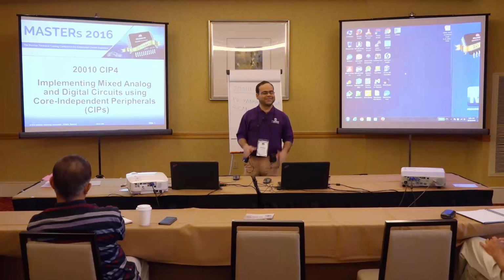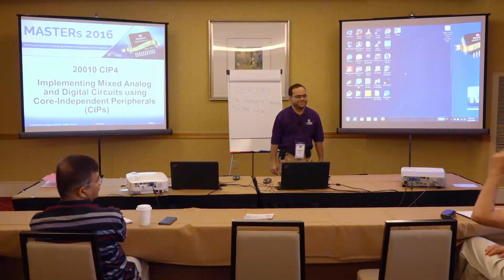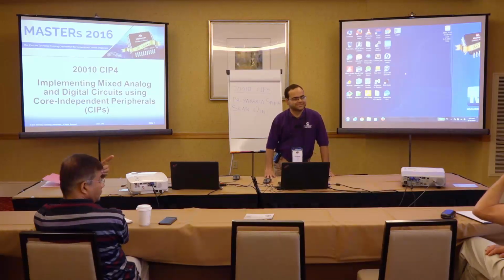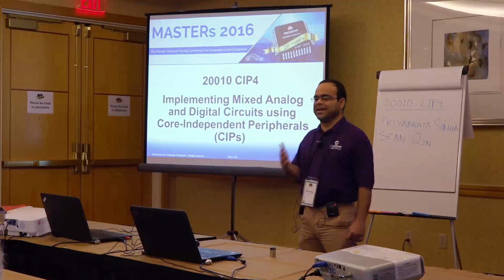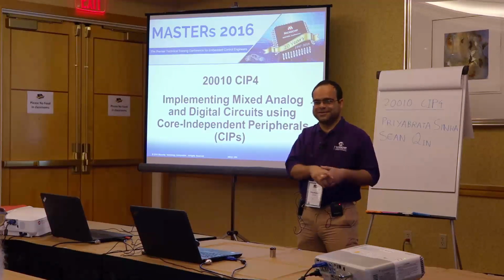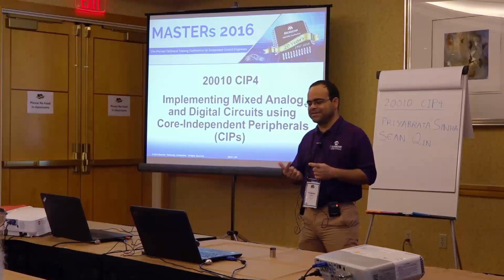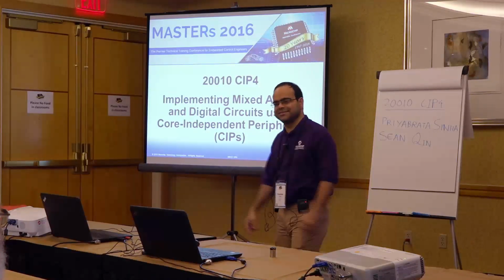Any questions on any of these modules? I have one. At times you've referenced a zero detect circuit. Is that a module or is that using a comparator? Okay, zero cross detect: is that a module or are we using the comparator? On the 8-bit devices, it is a separate module, and it's one of the core independent peripherals. On the 16-bit devices, we have to use a comparator. So it depends on the device.